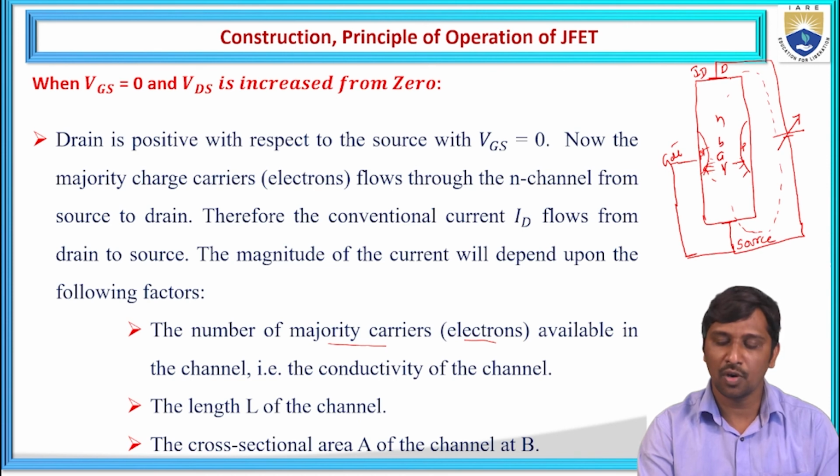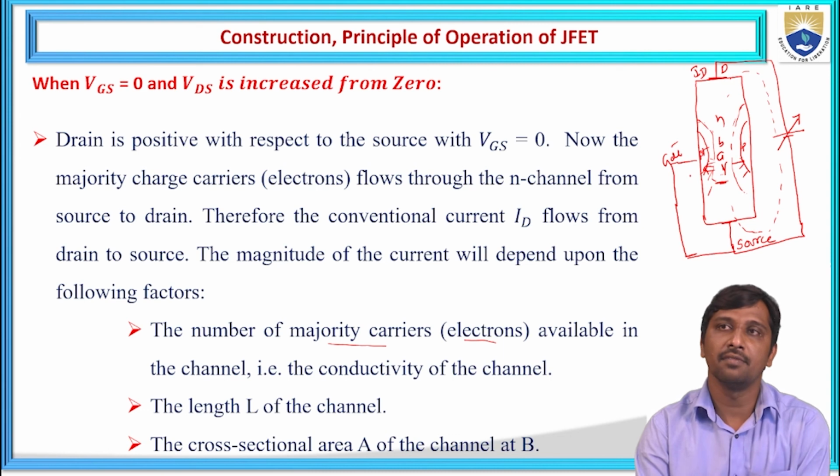Now, if we want to control the flow of current, we need to increase these depletion layers. So here we need to increase the depletion widths between these two heavily doped materials. To increase this depletion width, what happens? The flow of charge carriers, the concentration rate, will decrease, and the channel becomes very narrow. The widening of this depletion width can be done through reverse biasing. Hence, the gate is biased with a negative polarity for this N channel.